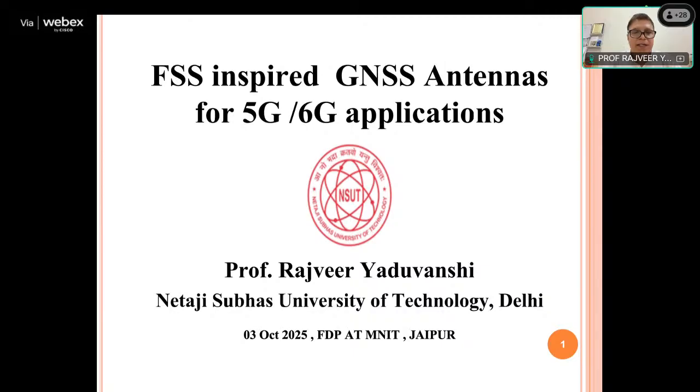The focus of today's lecture will be that we are designing an antenna at very low frequency. You are already aware lambda is equal to C by F. So the wavelength used to be huge, a very large profile at low frequencies, but I'll be showing that the same high profile antenna has been reduced to a low profile antenna using these frequency selective structures.